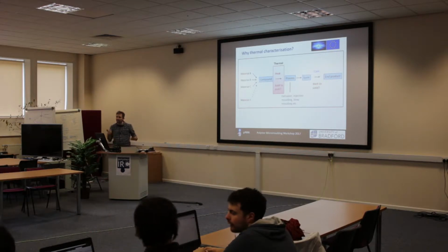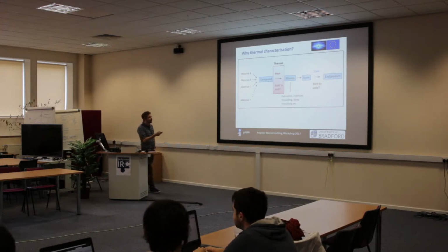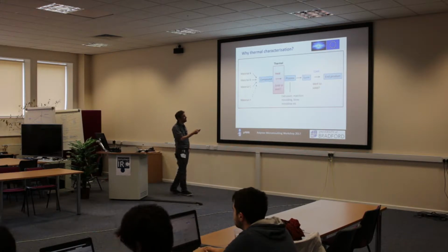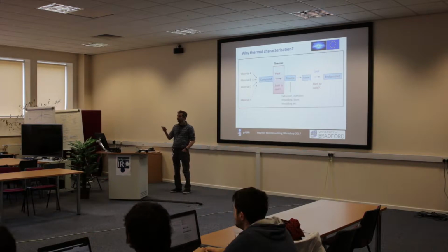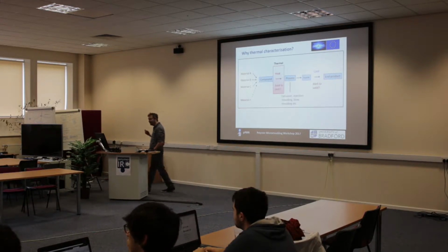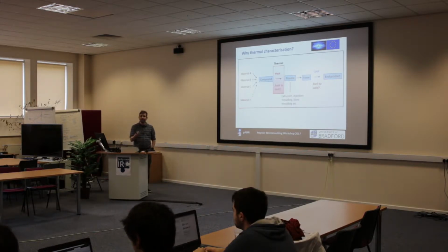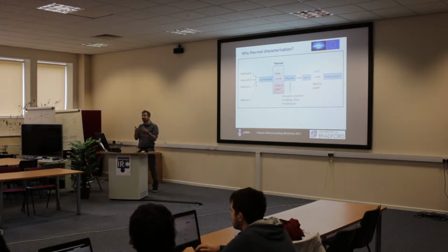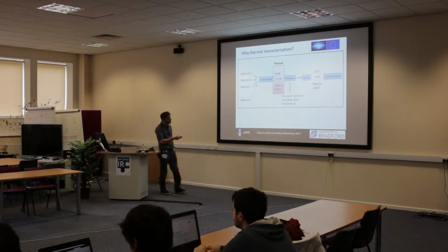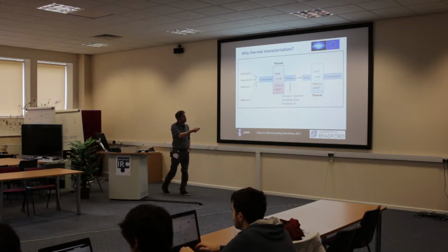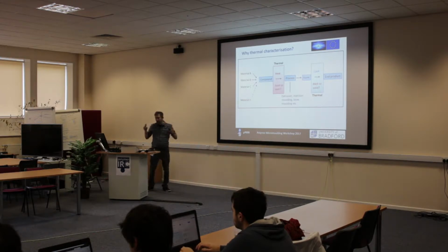We then process the material by flowing it through some kind of shaping device. Whether that's in injection molding, where the form is created by the mold, or in extrusion, where the form is created by the die. We then want to cool that down, to go from melt, or nominally melt, down to solid before gaining our end product.